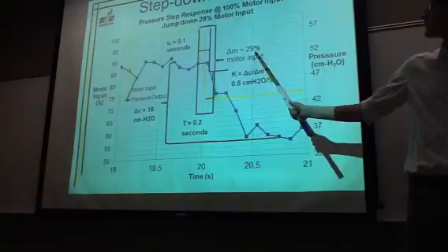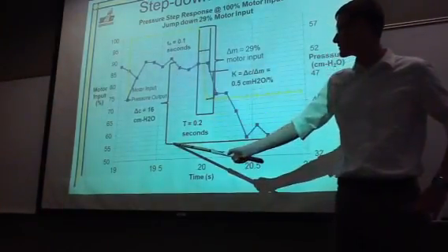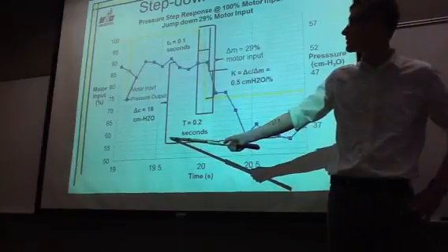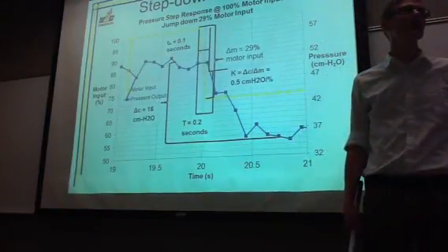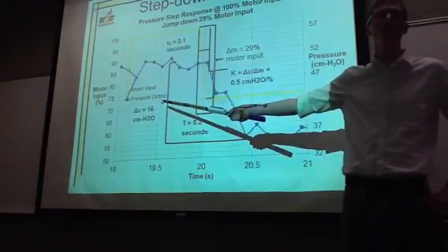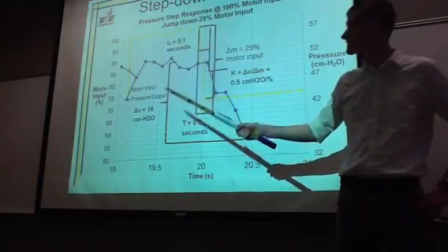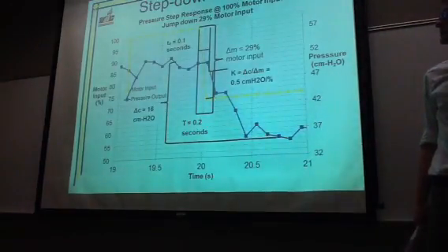percent power, which was 29%. The change of our output, which was measured in centimeters of water, was 16 centimeters of water. That is an average value. The average value change was determined by taking the average of the steady state operation leading up to the step response and the steady state operation leading after the step response,